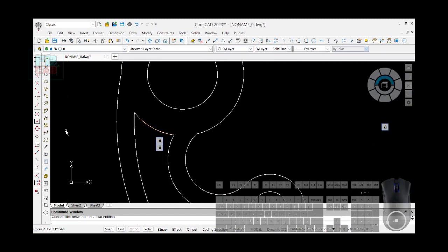I can't really tell you why it's not doing that. But what I know is there's always a way out. So we use our circle tool of radius 5. Dimensional constraint radius 5. Okay, press enter. So geometric constraint tangent, you pick this and this to be tangent, repeat this and this to be tangent. Okay, we can copy this from the center, and pick it here, doesn't matter, to this point. Geometric constraint tangent likewise. Pick this and this, press enter. I pick this and this.